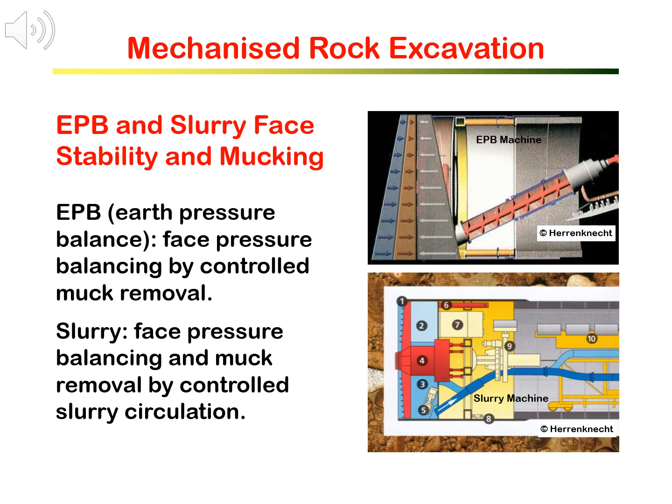With shield TBM, the shield gives good protection to the ground along the tunnel circumferences during excavation. However, with very loose and soft ground, the excavation face is also unstable and needs to be supported during excavation.